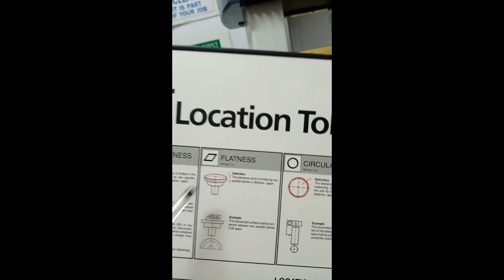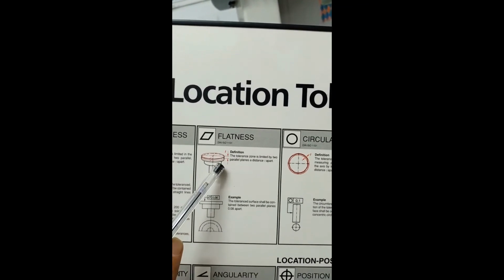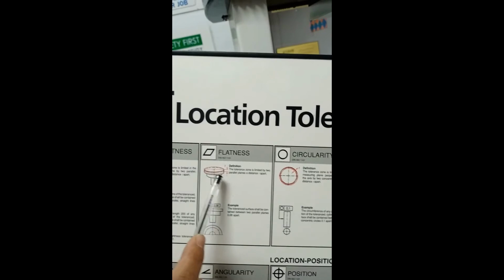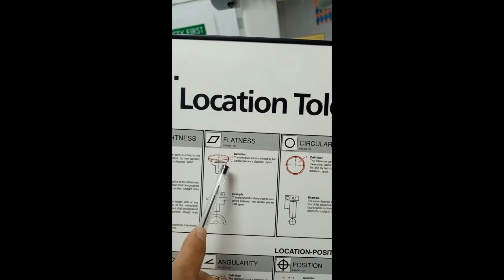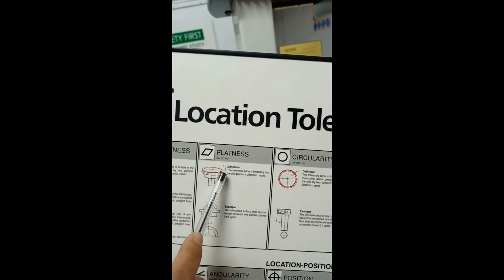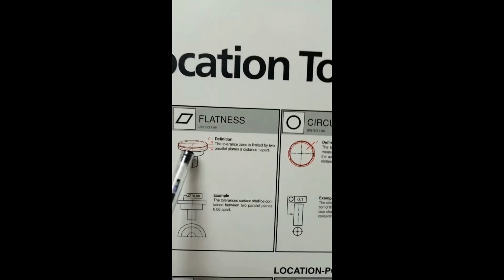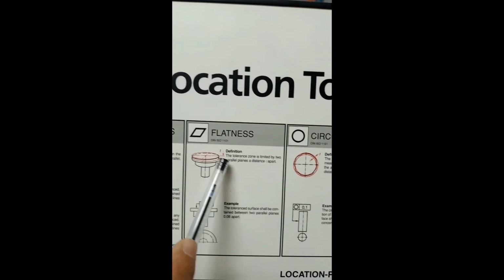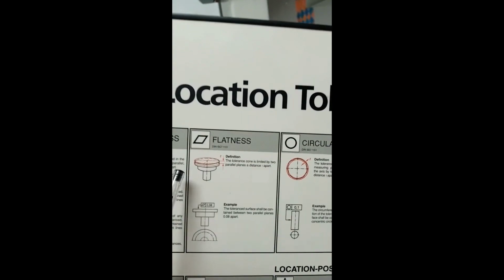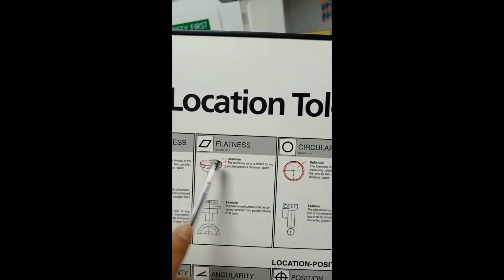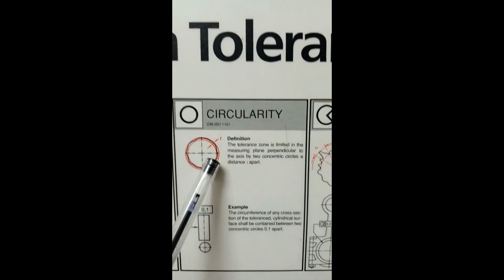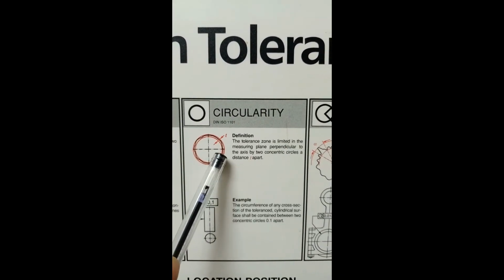And flatness also, you see, this is flatness. How is flatness calculated? Suppose this is your perfect flat object along the z-axis, with a lower red and an upper red. Your black line is the real object, and the lower red and upper red are formed by the different points. So the difference, the region between the lower red and upper red, is the flatness. If you want a perfectly flat surface, then the value between lower red and upper red should be 0. Here also, if you want a perfect circle, then the region value between inner red and outer red should be 0.